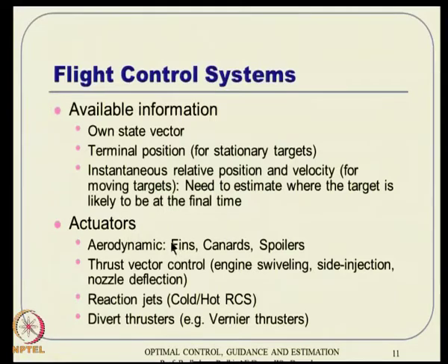Well, not really free, because you have to deflect the fins and things like that, but the lift vector is anyway there, you just have to tinker a little bit and you get a huge impact on your vehicle. Very little effort, but the output is very good. So, wherever aerodynamic controls are available, the recommendation is to go for that.